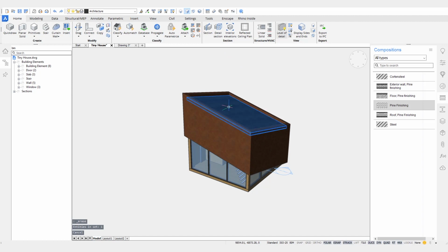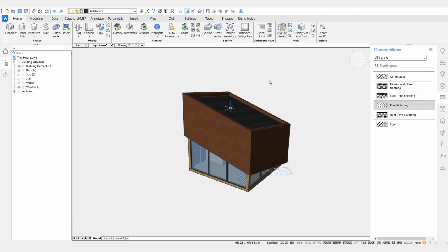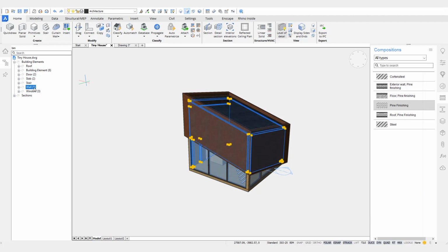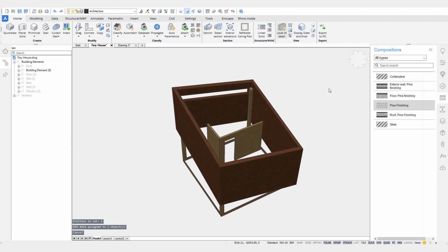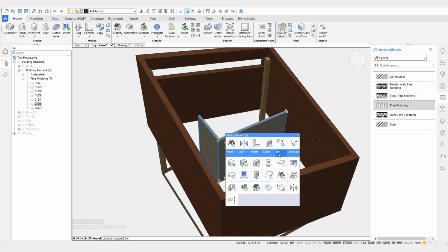So all of these things have already been classified. We have 3 windows, 7 walls, 1 staircase, 3 slabs, 2 doors, then 6 building elements. Building elements are basically the trash can of classifications. If you don't know what something is, just call it a building element and you're fine. But actually in this case I do know what they are. They're all coverings basically. So I'll just classify all of them.